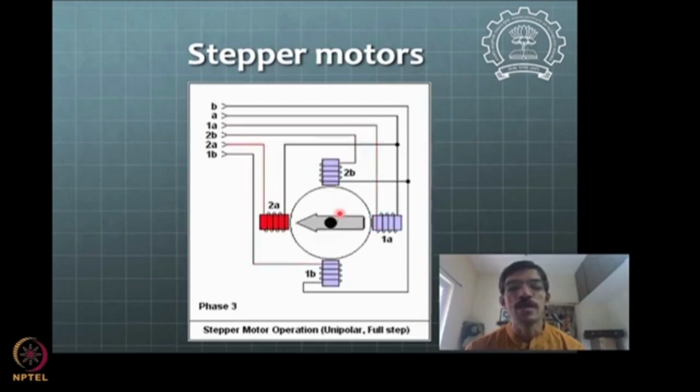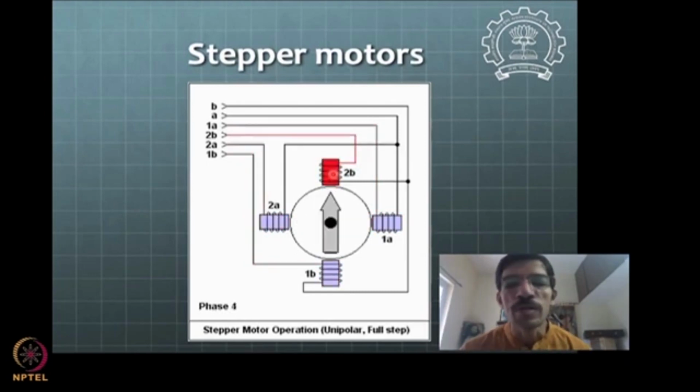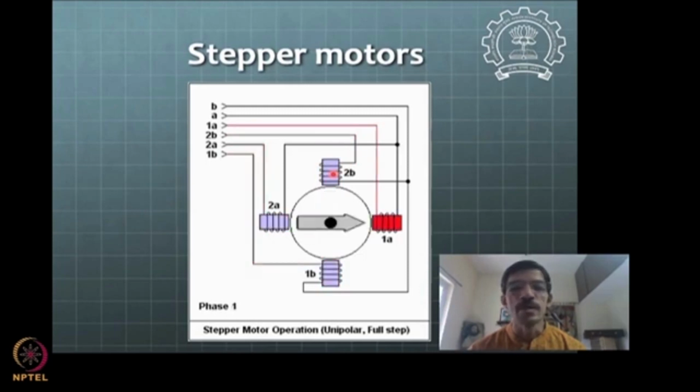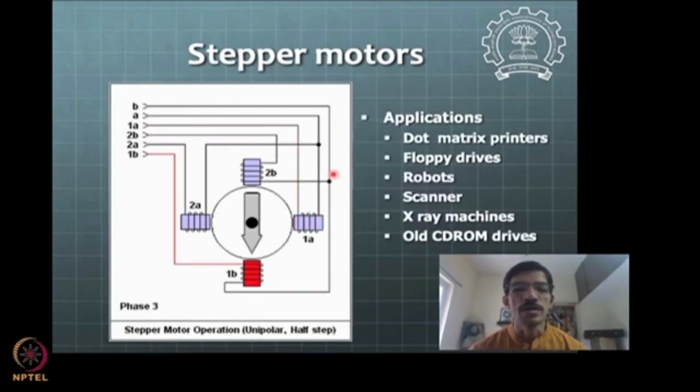One of the ways to get to these micro stepping modes, there are different micro stepping modes possible, is you control the voltage itself on each of the coils. Okay, so I'll tell you how we can control the voltage and do that. When we see this half step mode, you may understand things better.